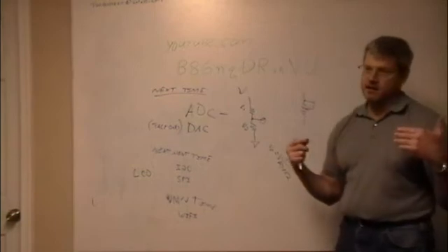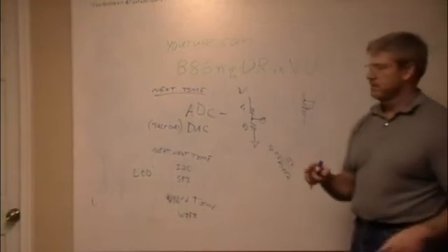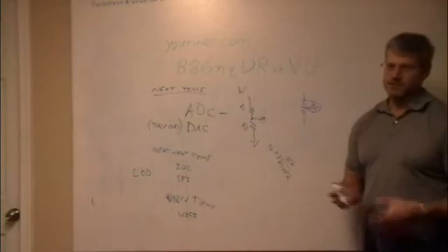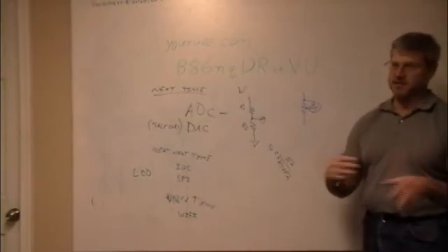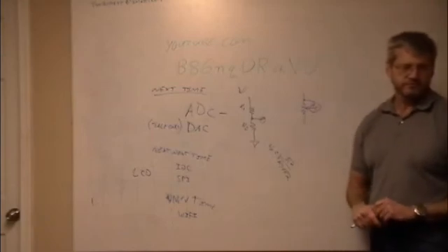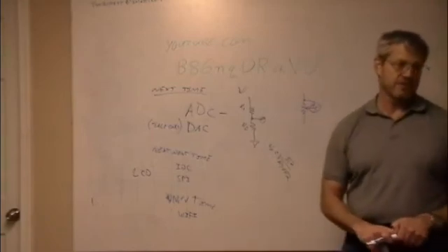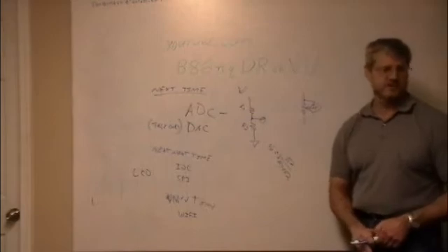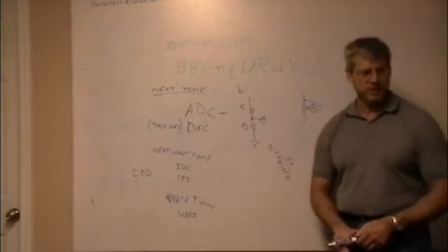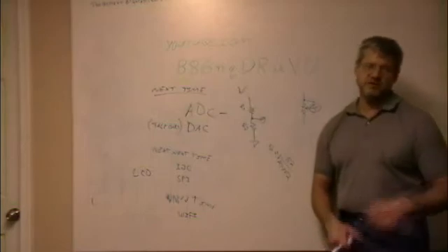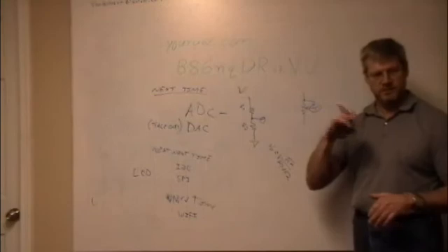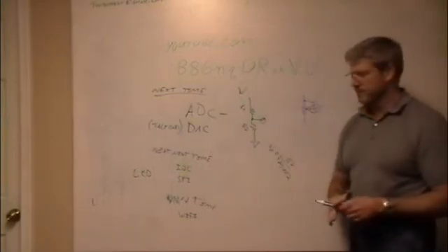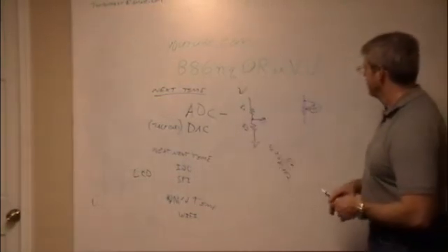Imagine that a thermistor is one of these, that the driving force here is temperature. It's all in the chemical compounds inside of it, and excitation values. Yeah, no, my 3D printer has a 100K. It has a PT1000 on it, or a PT100 is what they usually use, and a PT1000 is actually 1,000 ohms, and a PT100 is actually 100 ohms. I think it's 1K. Because 100K, there's too much noise. The trade-off with this thing is if it's too big of a resistance, then any little noise from anywhere makes it, even thermal noise becomes a problem at that level.